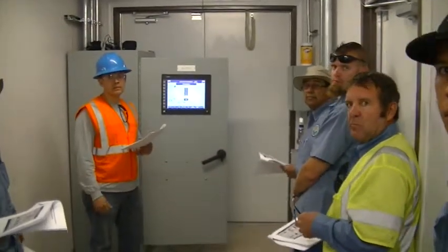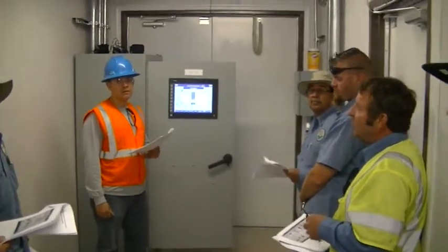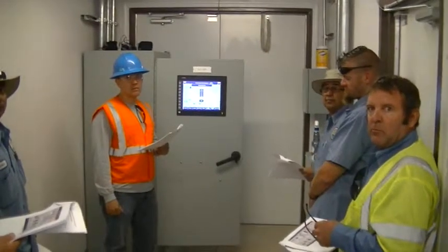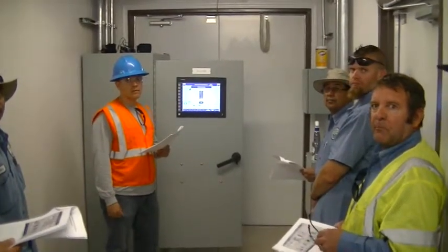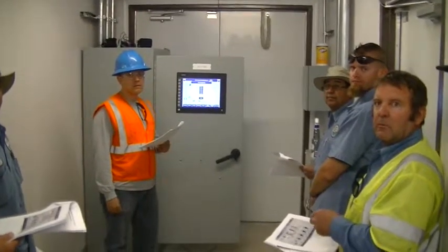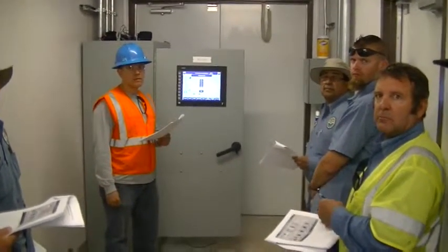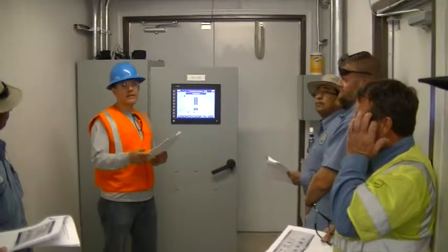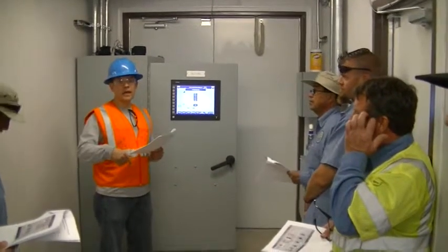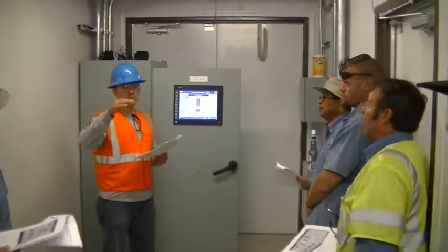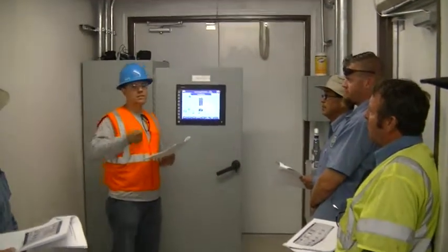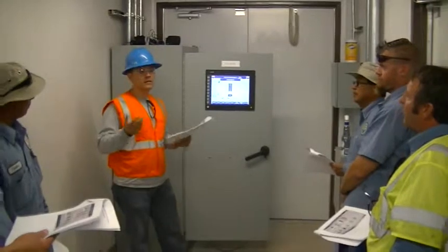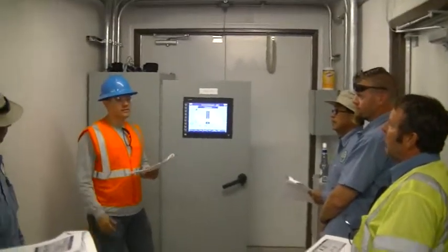You were saying it's already set up to do that, essentially? If the PLC reads off of the existing PIT that it reaches a low level, then it's also going to kick it out, correct? It will. But he's saying if that float fails and it's not a low level condition. Yeah, he was asking how can you get it to work? You have to jump it out at that point, because it's a permissive. Okay.